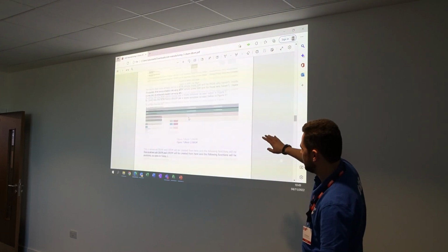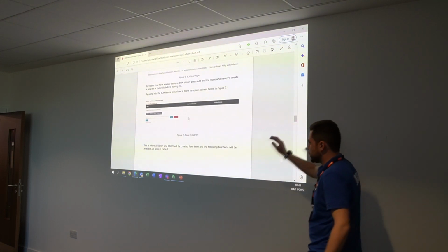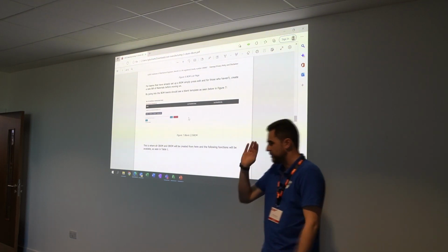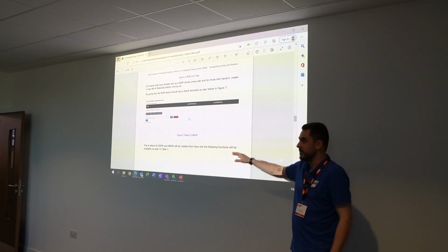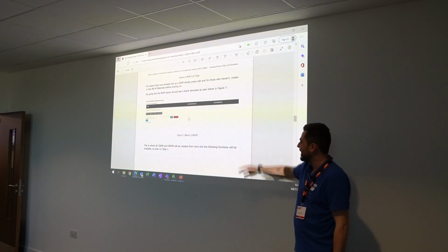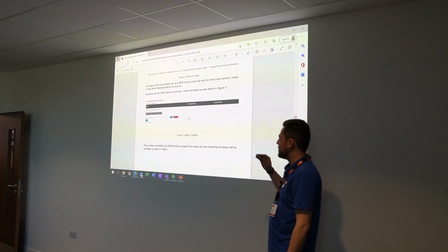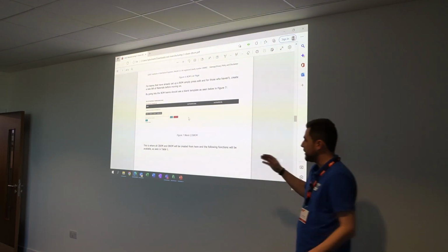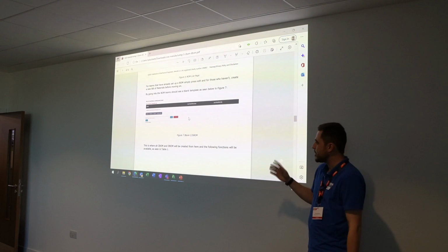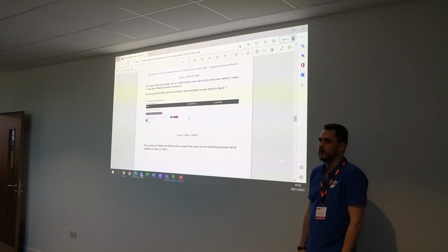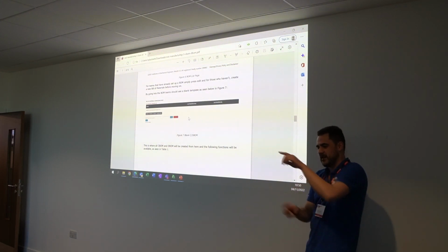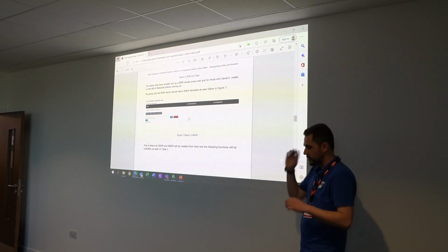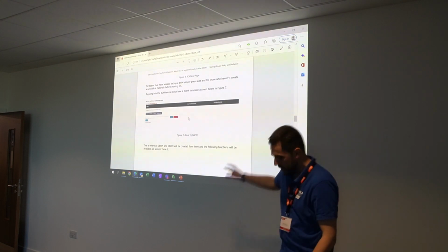That's the introduction page. That is the most daunting page you have. You know when you go onto Word and you're trying to write an essay and it's just the blank thing? Yeah, this is worse because you have to cost a whole vehicle on this and you start with nothing. So make sure you've thought about it. Whiteboards are your best friend with this. Sketch it out with a team before you just start throwing things in, because you'll get 700 lines in and go, oh, that doesn't make any sense because that should be there and this should be there, and you can't move them. You can move assemblies, you can't move processes and parts. So make sure you've sketched out a good plan before you go into this.